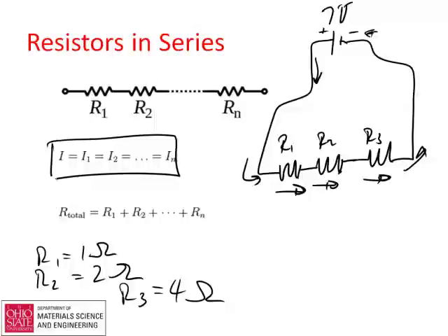So I could take a voltmeter, and this is something I would encourage you to do in your class. If you have wires exposed, and you're using low voltages like 7 volts, you can do this with a voltmeter like this. I could clip that voltmeter from here to here. Across these good wires, these are good conductors, ideally zero resistance, I would see no potential difference between here and here.